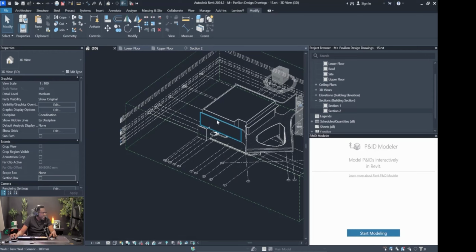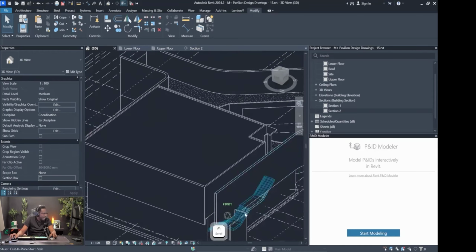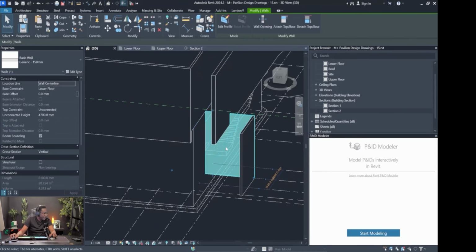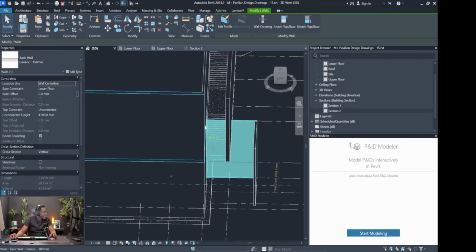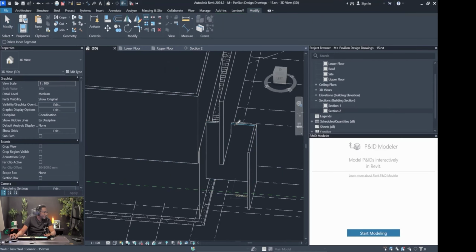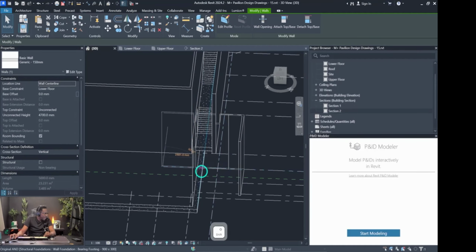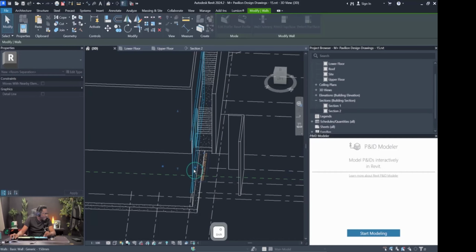So we pretty much have most of the walls. This section that's here, yeah, we're going to have to detach this wall, because this wall I believe is a low wall, so we need to break it away from the other wall. So I'm going to use the slice tool like that, and I'm going to pull this wall all the way back to here, and this wall I can align with this face here. And I'm not sure of the height of this wall. We can maybe for now make it the height of the floor, and same thing for here, right? So it's going to be something like that, right? It's going to be something like that.